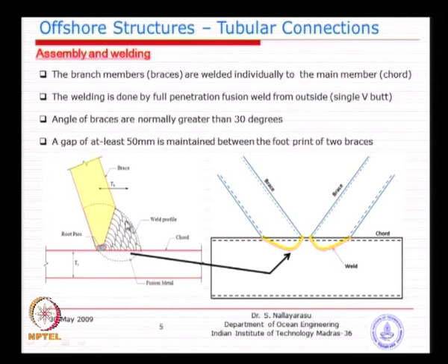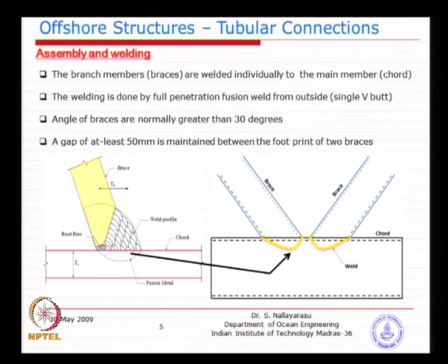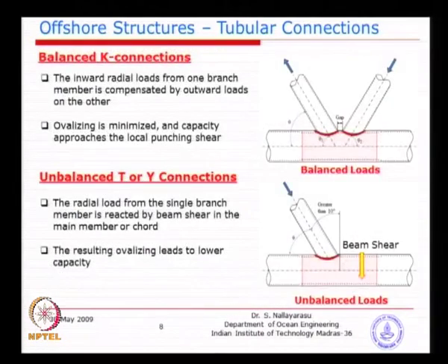the particular purpose is the profile of the welding. At the surface, if you look at a real photograph of welded surfaces, which I might show in one of the classes, you will see a lot of changes in the curvature. So, where the base metal joins the weld, you may not get a very nice clean surface, and that is where most of the time we see the stresses increasing because of the notch effect. We will see this in one of the finite element pictures later on.